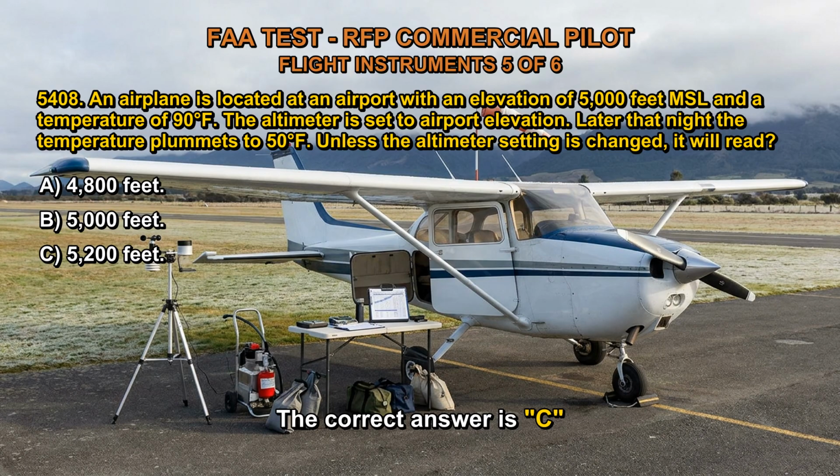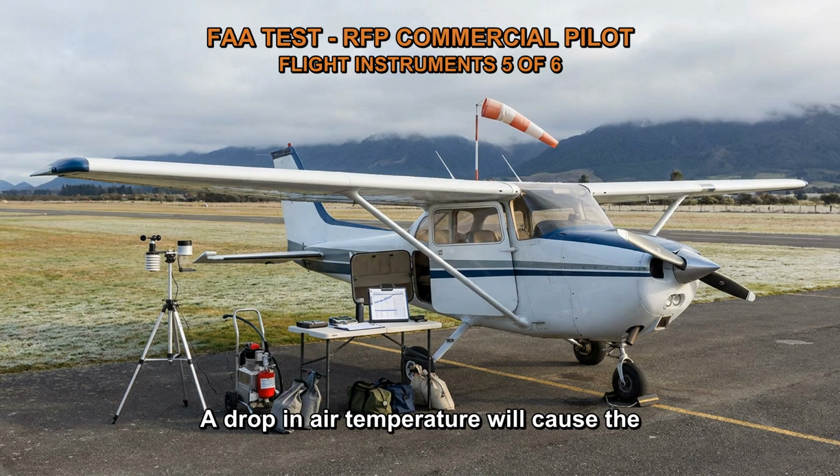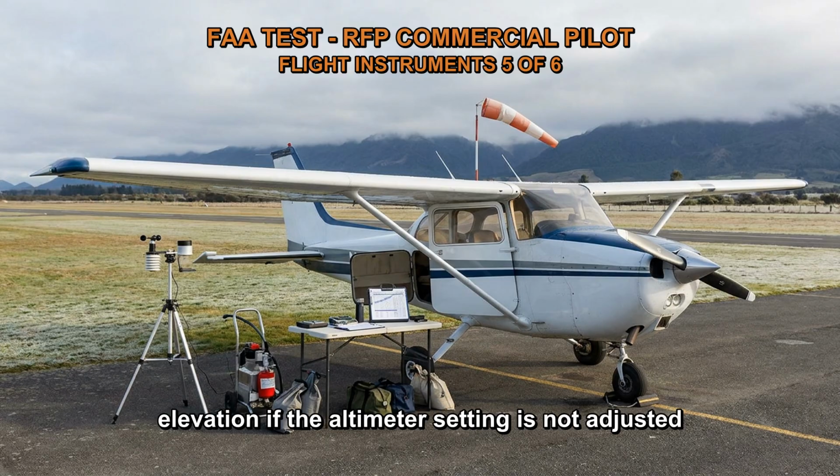The correct answer is C. A drop in air temperature will cause the air to become denser and lower the density altitude of a particular airport. The altimeter will read higher than the field elevation if the altimeter setting is not adjusted for the change in pressure.